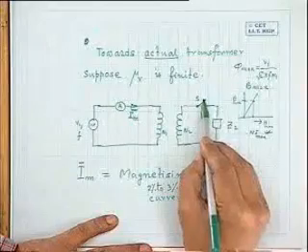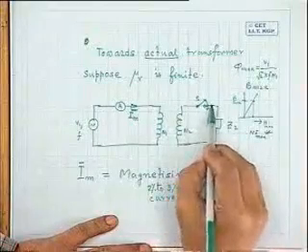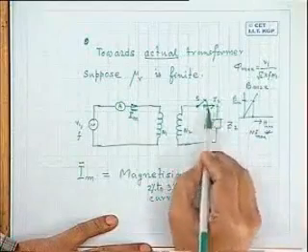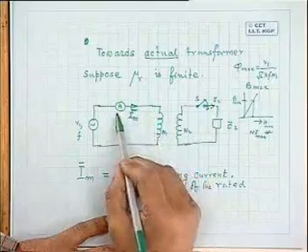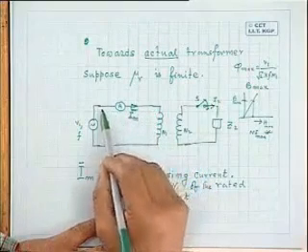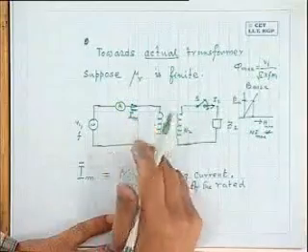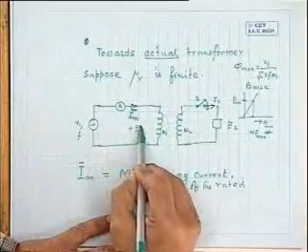Now the question is, for this somewhat practical transformer, I want to draw an equivalent circuit the way I have drawn earlier. How should I do it? Now you tell me, if I close this switch, there will be some current I2, there will be a reflected current I2 dashed here. What will be the ammeter reading? It will increase now. But what will be the total current drawn from the supply? It will be IM bar plus I2 dashed bar flowing.